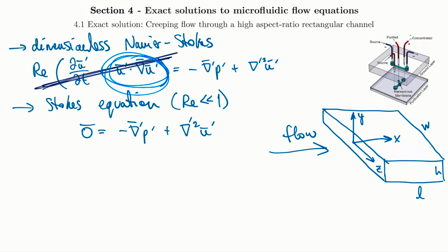And the geometry of that is also going to help us solve our equations here. Just a reminder too, because it's going to be important, we can see from the equation that we have the pressure balancing off with our flow. So in this type of channel, what you normally do is put something like a syringe pump. You'd have some way of changing the pressure. So the flow in the X direction is sustained by a pressure gradient in the X direction. That's worth writing out.